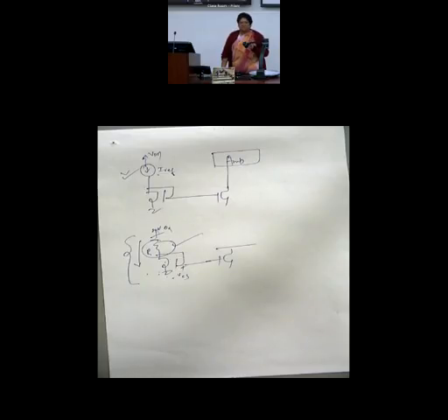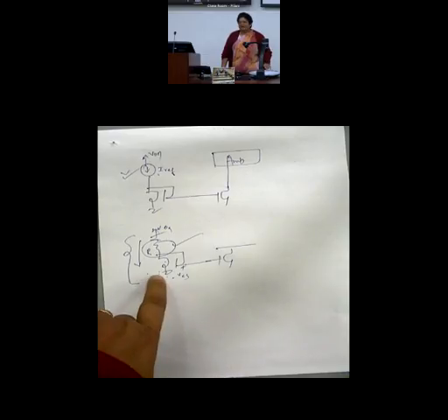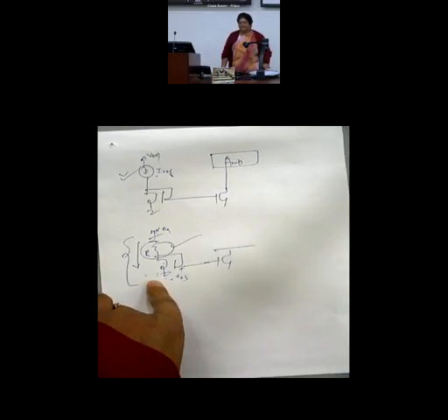What do you mean by a standard? Something which is not changing. It is immune to varying factors, which here are VDD fluctuations and temperature fluctuations. So if I use an R here, I cannot guarantee the constancy of IREF.